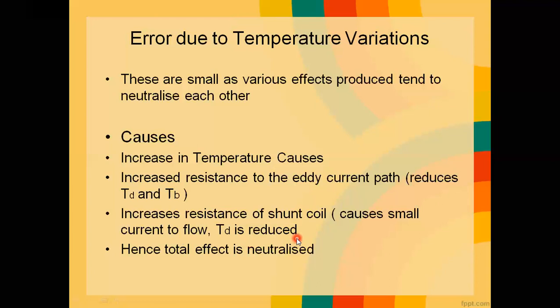Already there is going to be more resistance for the shunt coil, more inductance for the shunt coil, and resistance we try to bear in a bare minimum condition. And to achieve the quadrature flux to the voltage, we have arranged the copper bands. Again, because of temperature variations, if resistance increases, current or the flux magnitude will get reduced and thus the deflecting torque will get reduced.